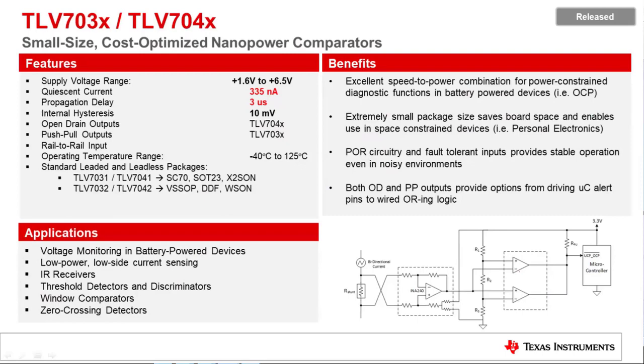And depending on external circuitry, that output can be high or low. And in some cases, it could even blip from high to low or from low to high. So that, of course, is not a stable environment, especially if you're using a comparator to control some kind of downstream FET, and you don't want to connect the system to power when you are not intending to.